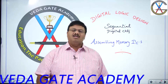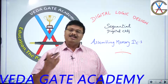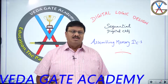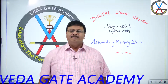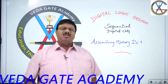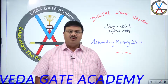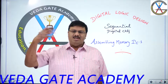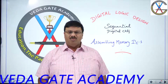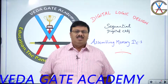And this is the inner logic behind why assembling plays a key role in the design of memories or multiplexers or decoders or any circuit, I can say. So assembling plays a key role compared to the design. Designing only a few standard size ICs would reduce the manufacturing cost of the system, where I am benefited as a user to buy the IC at a lower cost. And if my requirement is not directly available in the market, I would buy the suitable lower sized ICs and assemble them and use them. That's the basic theme of assembly.